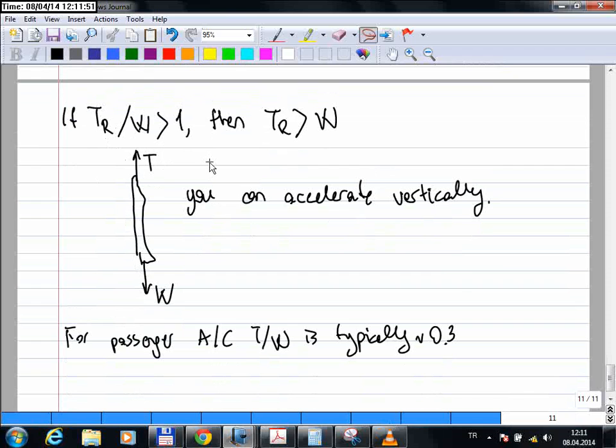So by thrust vectoring, what I mean is the pilot can change the direction of the thrust force. So he can make this like this, for example, if he needs to, or like this if he needs to, by changing the direction of the thrust force. So that will give him the authority to control the pitching motion, because he cannot use the elevators at all.